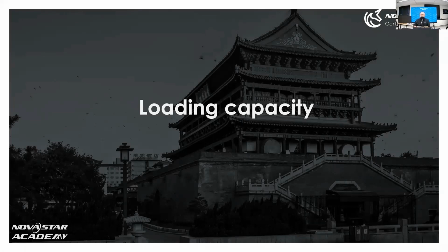You may wonder, okay, what is the parameter which you care about? The only thing which we care about is the total pixel number of the screen or the cabinet. So if the total pixel number is within our loading capacity, we can handle it. If that is overload of the loading capacity of one output, that means we need one more output, or we need